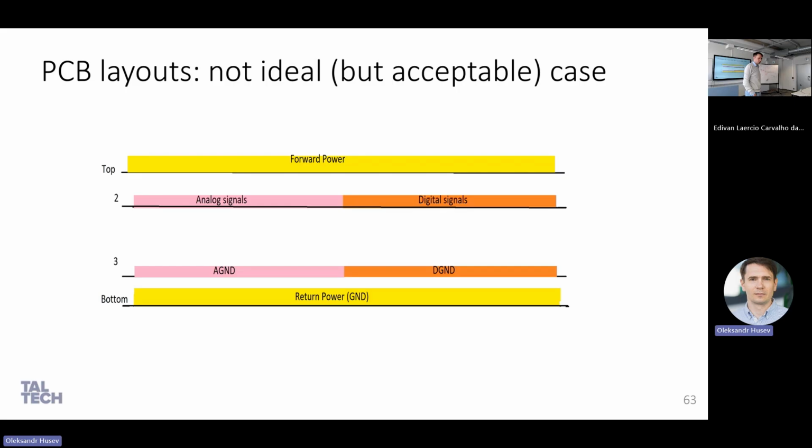Capacitance should be distributed properly. When we talk about switching, we should take care that capacitance is distributed. It means that if you have a switch and cell, and you have some long wires, it doesn't matter whether in PCB or not, and this switch and cell is connected to a capacitor that is located far away, you have this inductance.